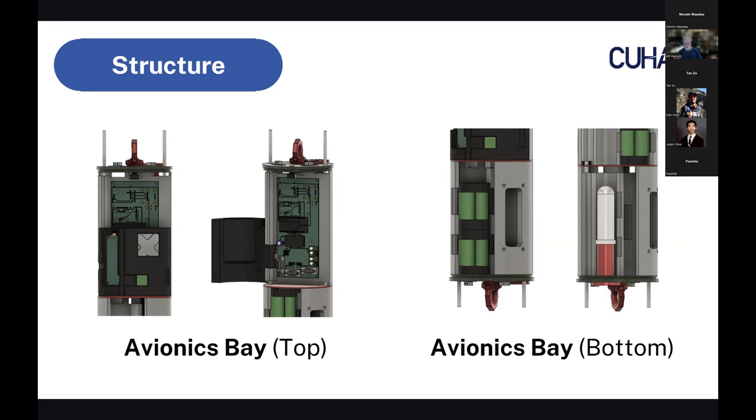The reason I check this is because in the past, when I've done post-flight data recovery, I've had more than one rocket with a 3D printed avionics bay that, when you opened the thing up, just came out in pieces because it wasn't strong enough to handle the vibration, or they didn't choose the right infill or the right material. But ABS should work well. Okay, good on you. Yeah, last year we also used this material, so I think it would work for this. Okay, very good.